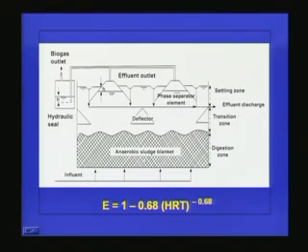So this is a figure we were discussing in detail last class. This is a schematic of an upflow anaerobic sludge blanket reactor, and we have seen how it functions. The wastewater is coming like this and the influent gets equally distributed at the bottom of the reactor, where the biological sludge, which is flocculent in nature, is present. As the wastewater passes through this sludge, which is nothing but active biomass, the biomass comes in contact with the organic matter and degrades it. As a result, new biomass is generated and the liquid comes up, along with the biomass and the biogas generated as the byproduct of microbial degradation. But if the solids escape along with the liquid, then the efficiency of the system will come down.